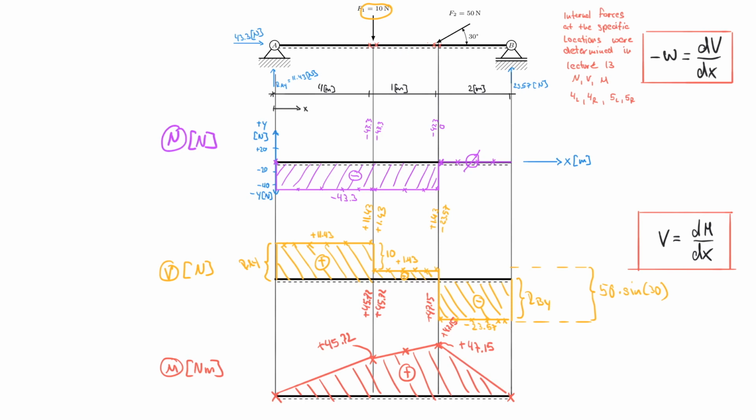And that is what we defined as positive moments. And therefore, you can take this here as an indicator that we answered this correctly, because you can physically say that this is pushing down, this cannot move, this cannot move, and therefore you must have a smiling beam, and the positive here indicates that it is a smiling beam.